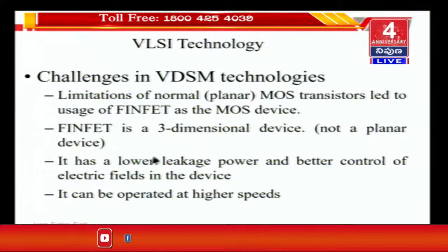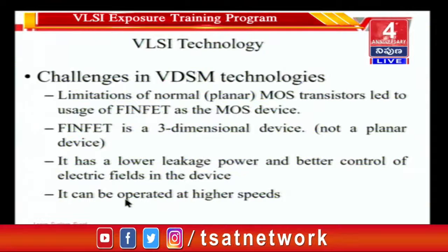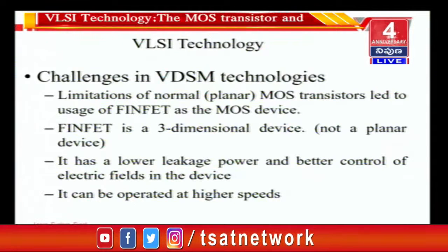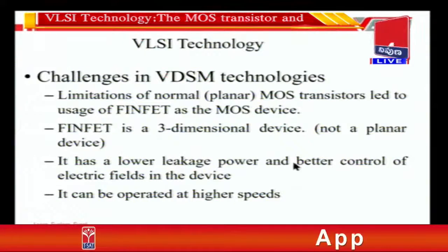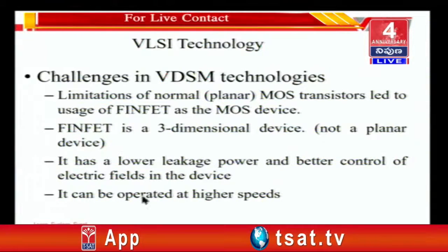And because of lower leakage power, a FinFET can also be operated at higher speeds. Because of the better control of electric fields, both these factors contribute to higher operating speeds for the FinFET.